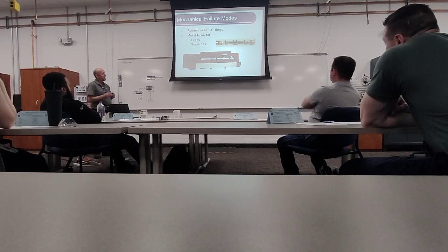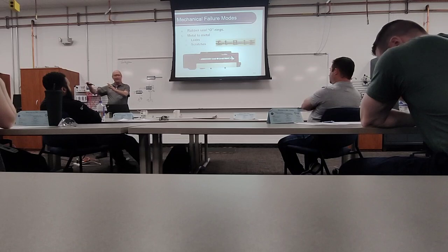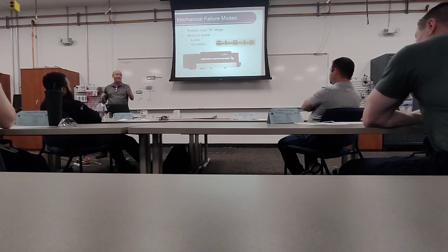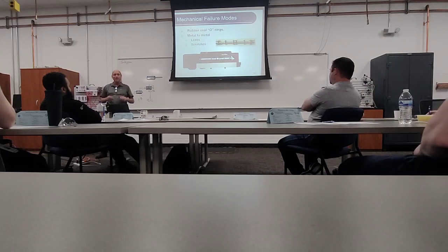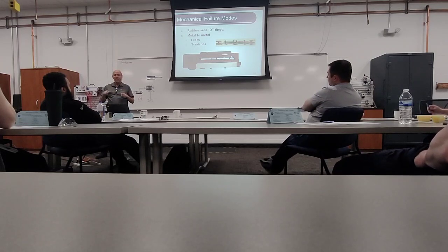O-ring type, we're gonna tell you to throw away, and I'm gonna tell you, keep some in a box, because if you get to the point where you can't get a valve and your machine's not running, you can't get one for a week, I would take it apart, clean it up, put it back together, and try to make a valve work. Somehow or another, I'm getting my process to work. What I would never do is call that a fix. That's a temporary Band-Aid, get the valve on order.